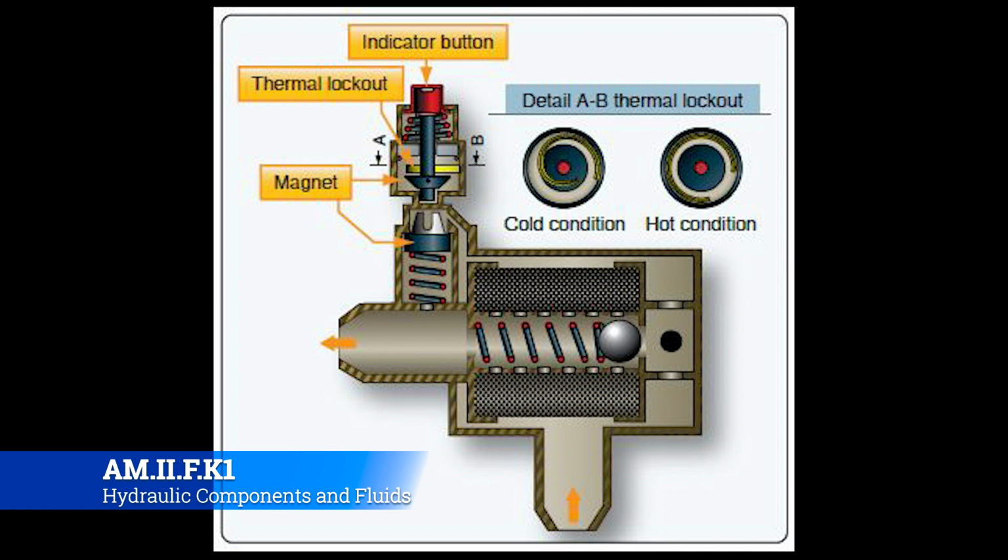And so typically what happens there is that there's something that's gone bad. Almost every single time I've ever worked it, the hydraulic pump starts to fall apart on the inside. It puts a bunch of trash into the stream of hydraulic fluid that starts to be caught inside of the filter. The filter's pressure gets too high, and then it causes the button to pop. Now, once that button's popped, one of two things could happen. Either A, you could get an indication in the cockpit that says, "Hey, look, this filter has been bypassed," and whenever the plane lands, the helicopter lands, they're going to contact maintenance to go and see what happens.